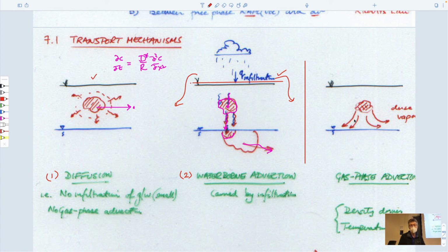The model we looked at for these last results is a model that also deals with dense vapor migration by these vapors being denser than air and therefore also sinking down by advection. So I guess this plus infiltration would give the maximum loading, because it would give diffusion which was faster than this case, because it would be accelerated by the fact that the dense vapors would fall under their own density, and they would be a more efficient transport mechanism than just diffusion alone. Advection is always much more effective than diffusion. In this particular case, the advection is driven by the negative buoyancy of the vapors. In this case, the advection is driven by the infiltration of water and the dissolution in the water arriving at the water table. So they're just a mixture of different mechanisms.